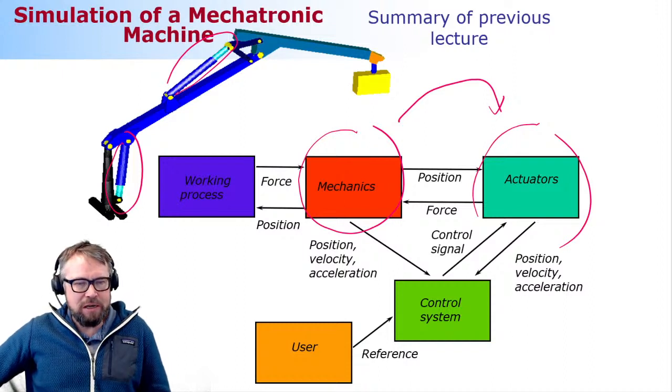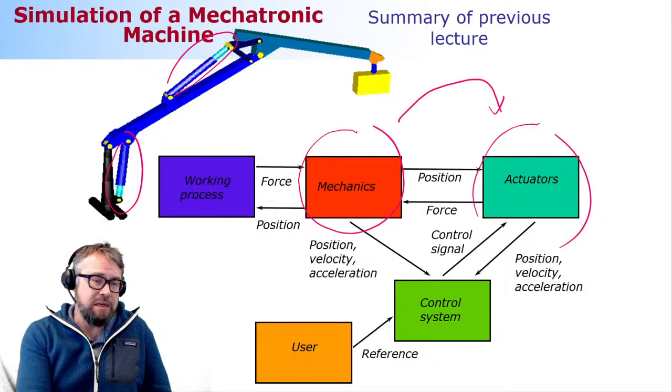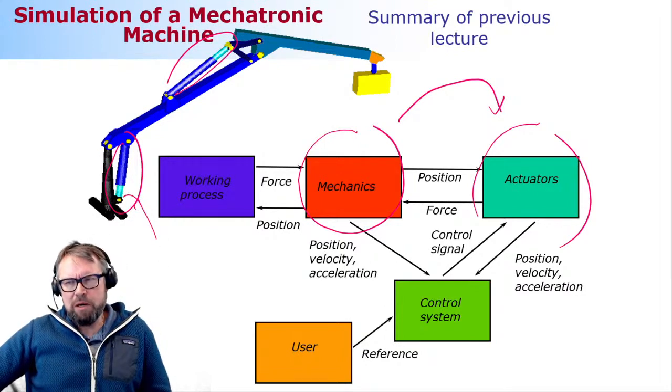Okay, so water hydraulics was very fashionable a little while ago because of this environmental aspect. Whenever you have hydraulics, you have leakage. That's almost like a rule of thumb. It's not as big a problem as it used to be, but still hydraulics is nasty, conventional hydraulics I mean, because in conventional hydraulics you have high pressures, 200 bars or more, and those hose connections and other connections are vulnerable to leakage.